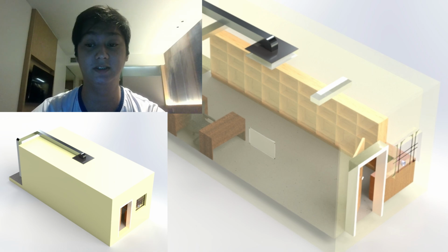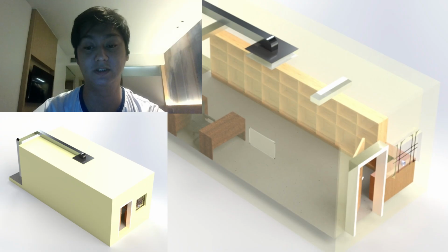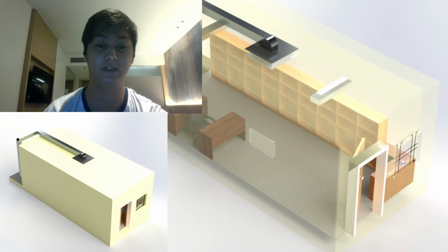By using a ducted system, we gain a higher static pressure. This allows us to position the supply diffuser strategically across the ceiling. This guarantees that whether you are sitting at the desk in the back, or standing by the cabinet in front, the temperature is consistent. Furthermore, it's about aesthetics and acoustics. Concealing the fan coil unit above the ceiling removes the visual clutter, creating a professional look. It also significantly reduces indoor noise since the mechanical parts aren't in the occupied space.